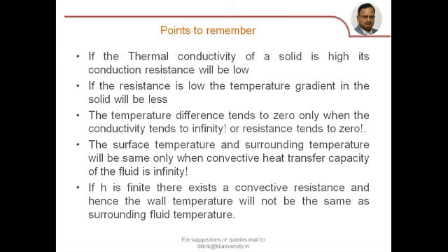No fluid has infinite convective capacity, hence there always exists a temperature difference between the surface and surroundings. They never become the same. Next point. If h is finite, there exists a convective resistance, and hence the wall temperature will not be the same as the surrounding fluid temperature.